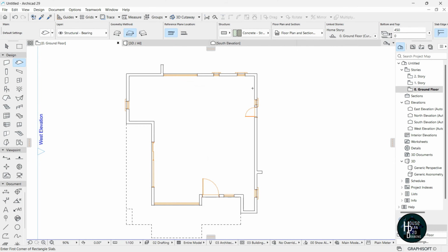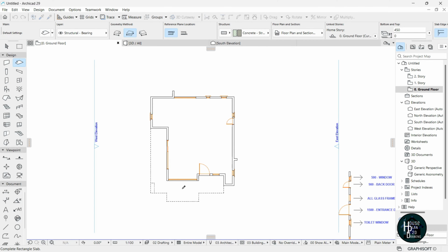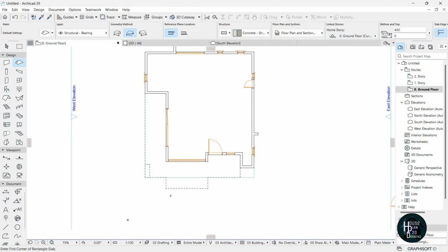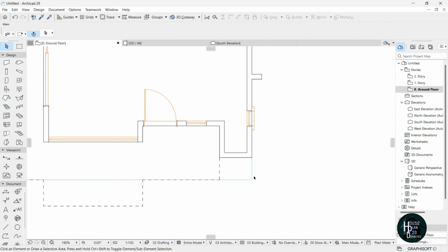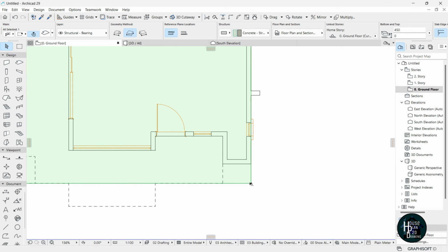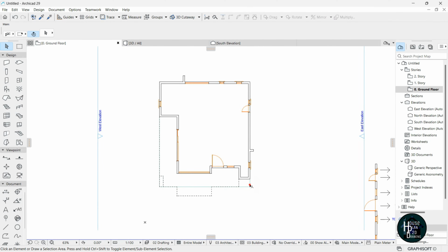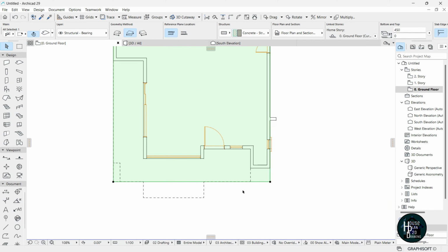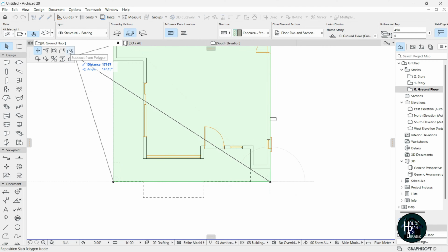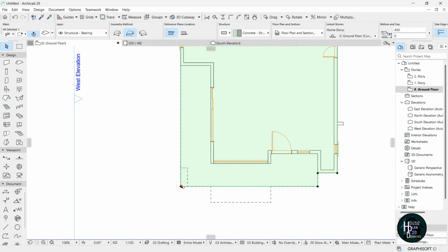Once you finish doing that, just click this side, drag it like this, then click. Okay, now you want to try and make sure that what you just did, as you can see, this is a line that is outside. Okay, this is a slab that is outside. So you want to try and make sure that this conforms with all of the edges of this particular. Okay, so you want to click this and let's cut out the shape away. So you want to click on the subtract from polygon, click this and then click this.